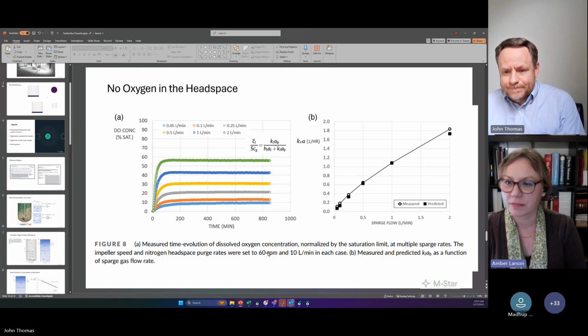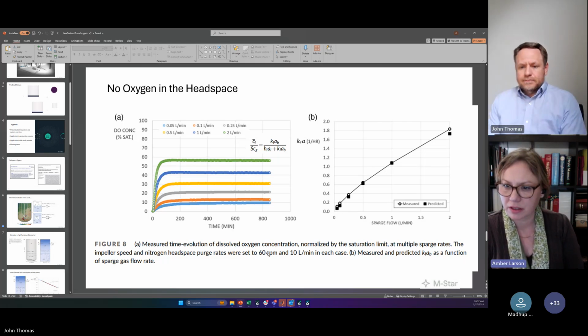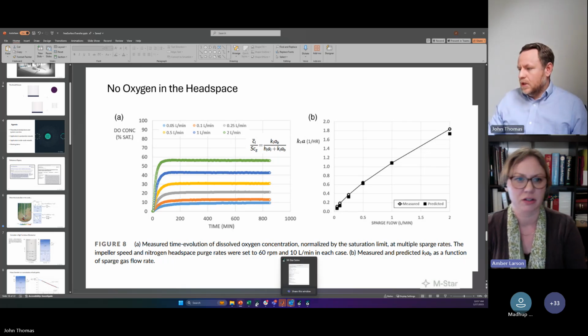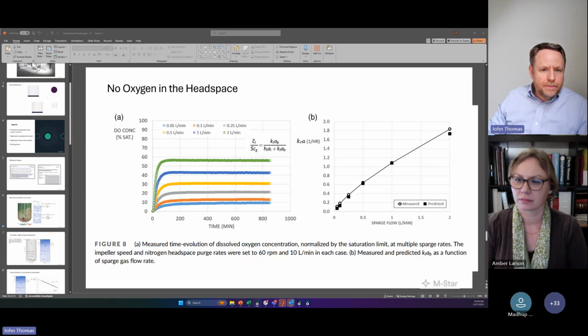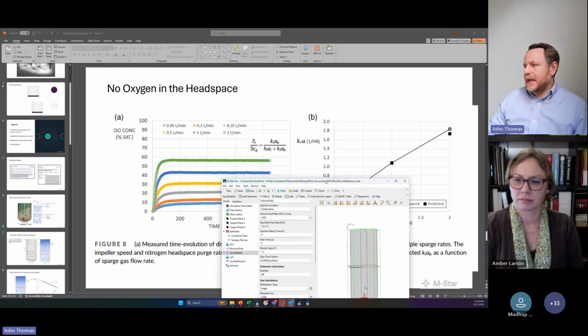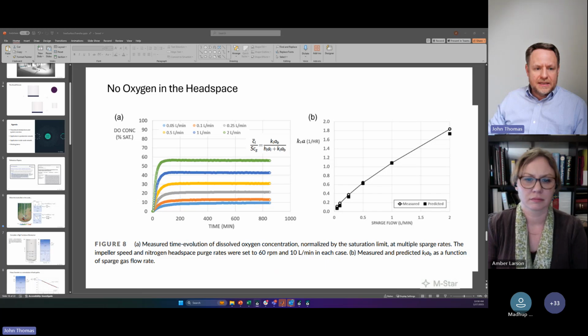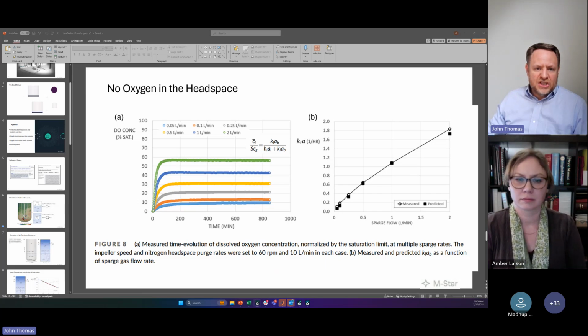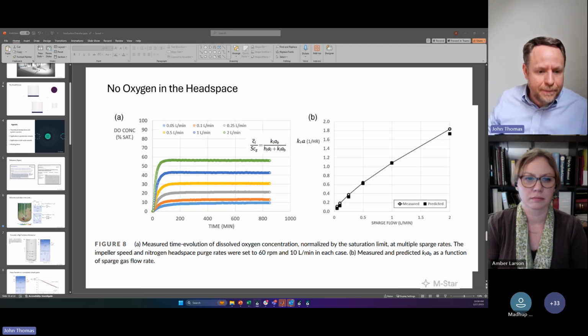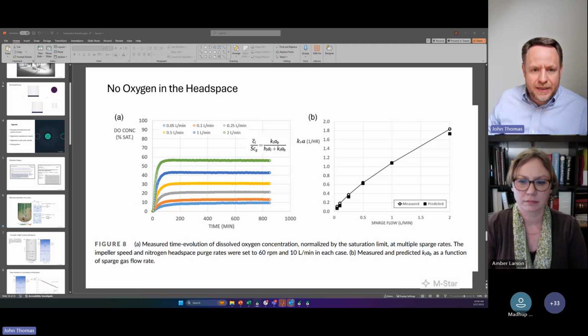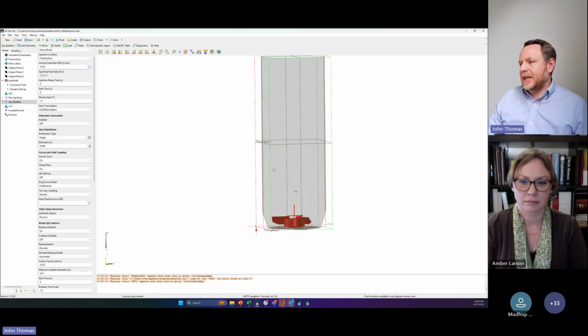Okay, next question. How do you compare DO measurement from sensors, which is relative as a percent, and the absolute DO concentration from CFD simulation? You just divide it. It's something people do all the time. Here's a case. Let me just sanitize this name real fast. But it's just a normalization, the same way the sensor does it in some sense. Okay, here we go. It's not uncommon.